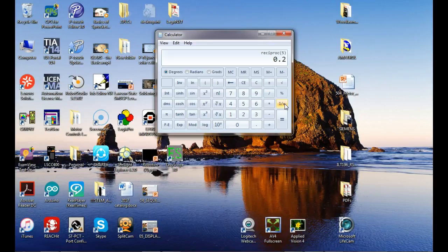So if I take this time, which we measured as 75 microseconds, and I say 75 times 10 to the minus 6, and then I take the reciprocal of that, it tells me that the frequency is 13,333 hertz, or 13.3 kilohertz. Now, this function generator has a special device in it called a frequency counter, so it's going to display the frequency for me. So what we did, we just calculated it, right?